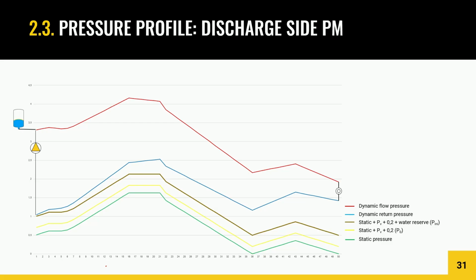At full load, the pressure profile looks the same as with suction side pressure maintenance if the vessel is set up correctly. The difference appears at partial load. We'll see that next.